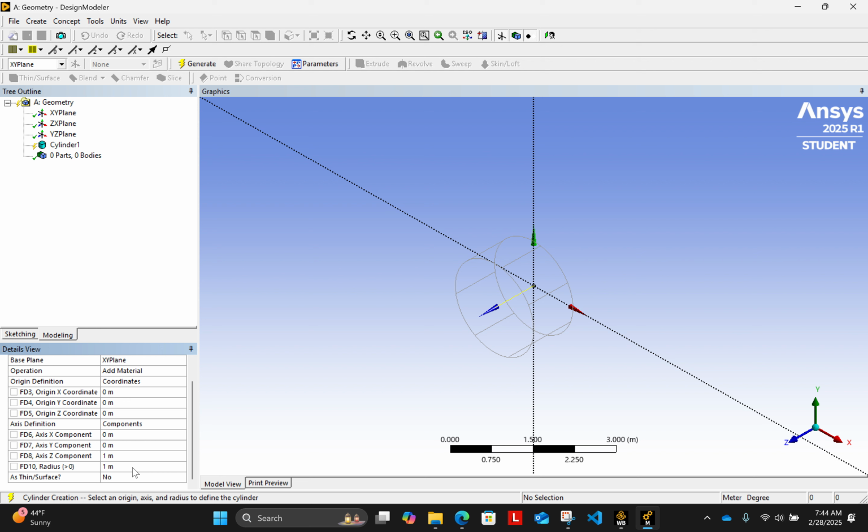1 meter radius for a traffic light beam is a little too much. We want to reduce this to 30 centimeters or 0.3 meters. Okay. And the height of it, 1 meter is too small. 1 meter, if you're not familiar with the metric system, is 3.3 feet essentially. That's way too low. We want to increase this to, I guess 8 meters should be fine.